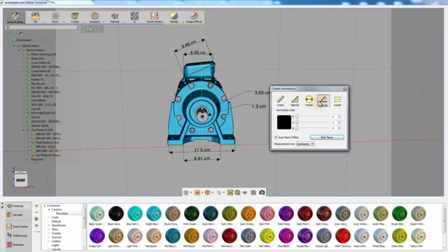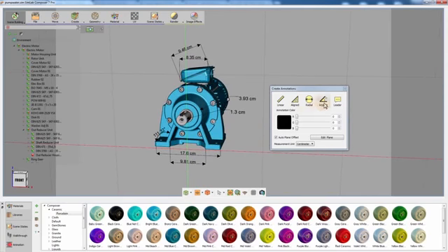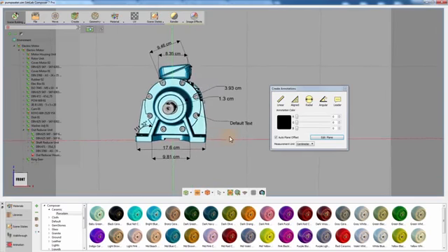Click on the Angular Dimension tool and click on an edge to set the first line, and then click on another intersecting line to measure the angle between them. Create a leader annotation and click on a surface or an object to create an indicator pointing towards it. Click several times in the 3D area while moving the cursor to determine the path of the indicator for the leader annotation. Then click on the green mark to confirm its location.